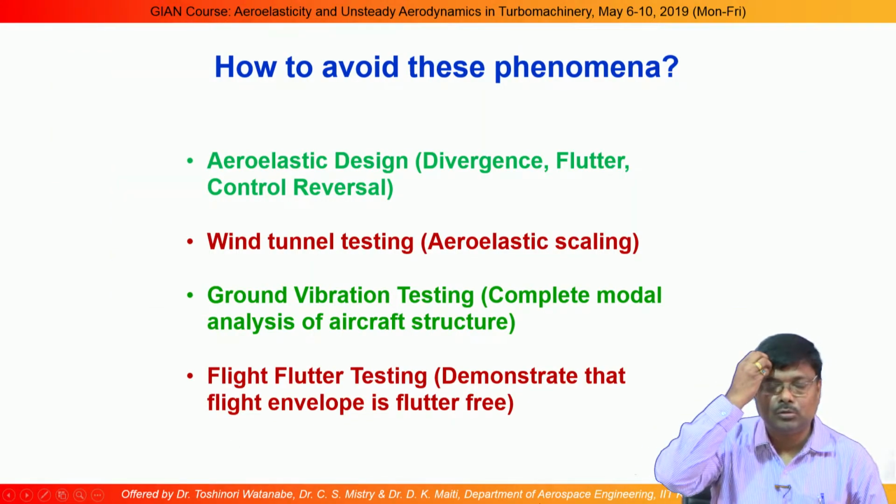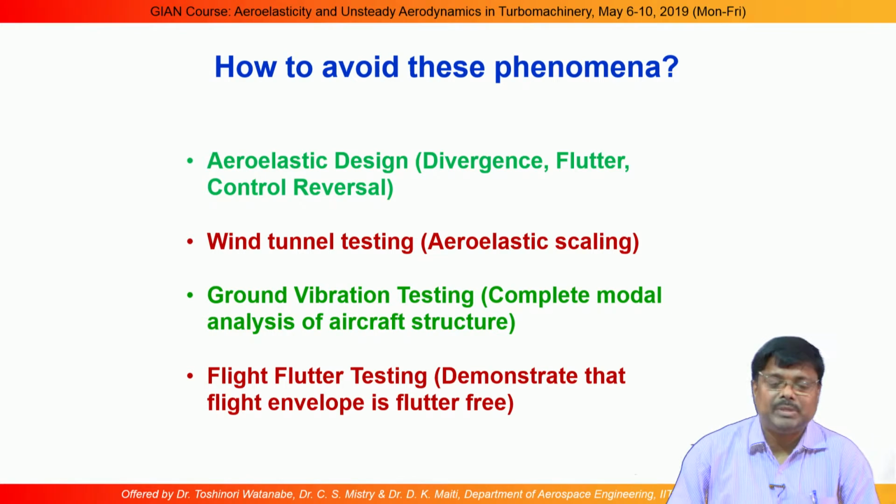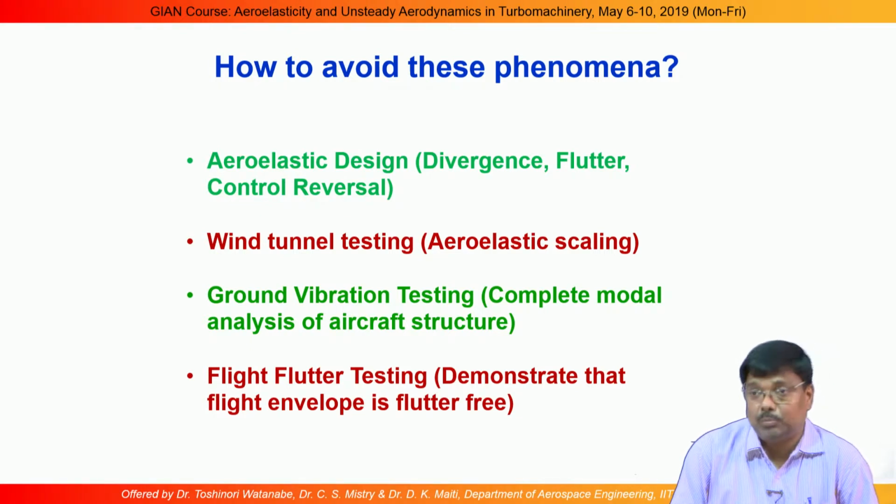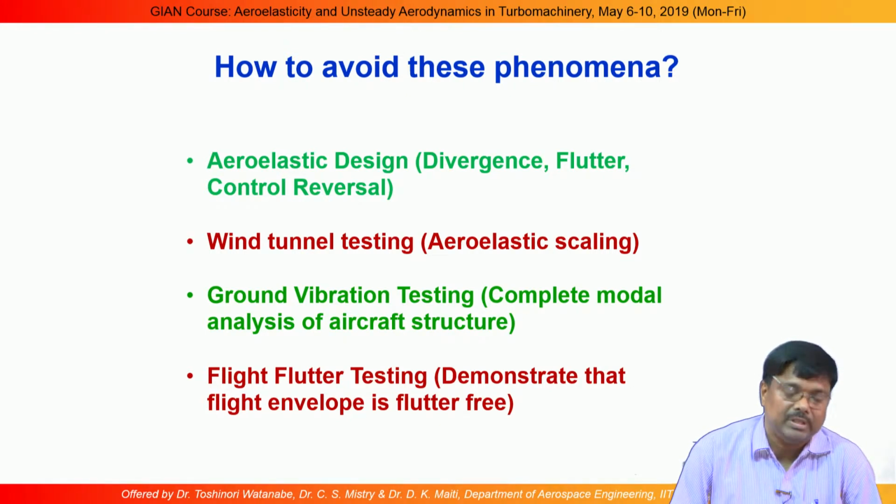So how to avoid these things? Basically we have to consider the aeroelastic aspect during the design phase, and obviously we have to do some wind tunnel testing, because in analysis we have a lot of assumptions and that may not be accurate enough. But analysis is important; without analysis we cannot proceed to the design.